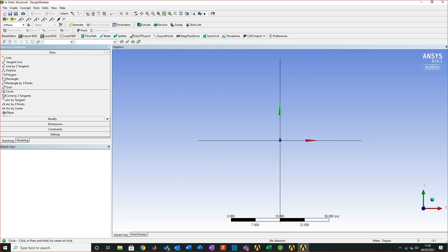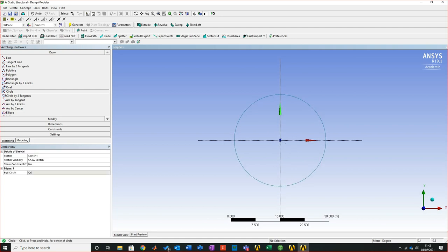So what I'll do is left click once, drag my circle out, bring my cursor back in, left click once again, and left click again to finish it. So that's me clicking and not holding or dragging anything like that. Some of you who've done CAD will know that you can normally left click, drag it, and then just let go and it releases it. This is a bit more primitive than that. So I'll bring that out and I'm just going to put it like that. So I've now got my two important profile sketches.